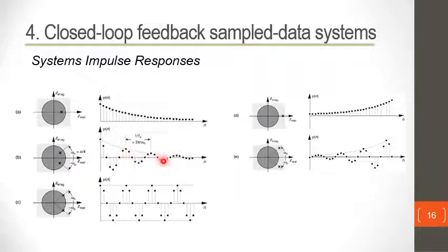You have that nice oscillating response that damps off. But if they're on the right, but outside the unit circle, then they will tend to blow out into instability because this transfer function will be unstable. And then if you have them marginally stable, then you will hold on to a sine wave or a cosine wave that doesn't die off. So it won't damp off, because it's just on the boundary and it's marginally stable.